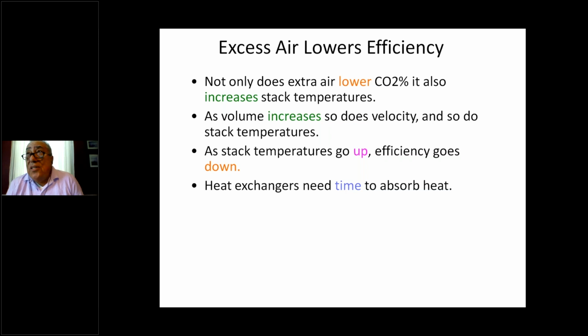Heat exchangers need time to absorb the heat. The longer that the flue gas can stay in the appliance, the more heat will be extracted. One of the reasons why your 3-pass boilers are so efficient is that flue gas stays in the appliance longer. And by the way, this is one of the reasons that we do that draft test.